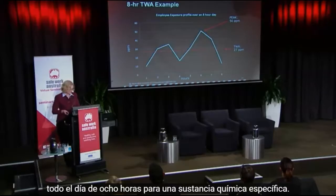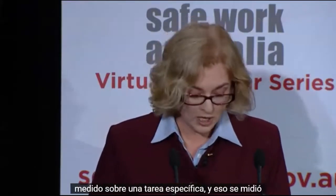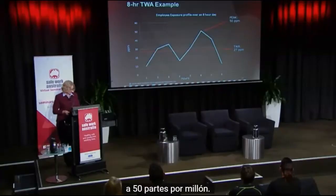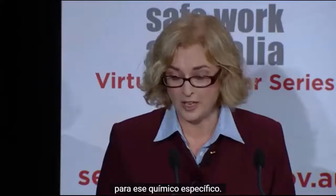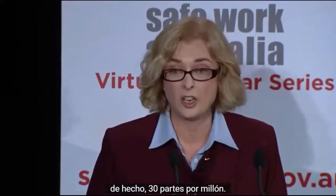In this instance, the worker's exposure averaged over the whole day is a time-weighted average of 27 parts per million. But the highest peak can be seen, which is the exposure measured over a specific task, and that was measured at 50 parts per million. Now, these measured values can then be compared against the relevant exposure standard for that specific chemical. In this case, the TWA exposure standard is in fact 30 parts per million.